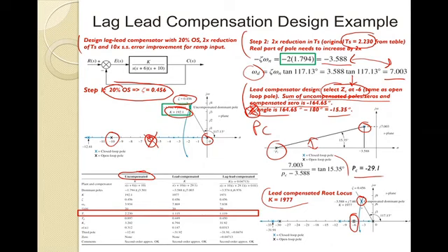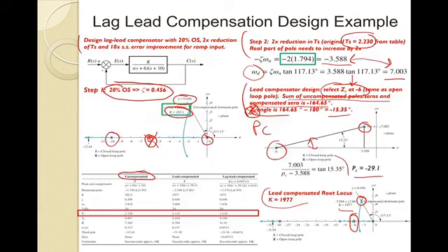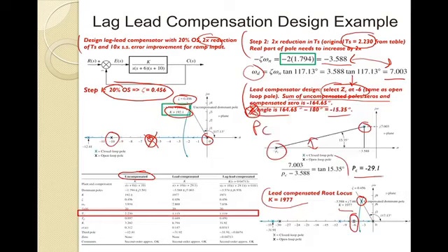As I walk through this, I have a pretty high gain here associated with that lead compensator. I then do my simulation, and I can compare the uncompensated system here in black versus the lead system that I'm showing here in blue. And what you'll see is the settling time has indeed come down by a factor of 2. 2x reduction was our goal. And again, you can see this if you look at the table. Visually, it looks like a factor of 2, but here on our table, you can see that factor of 2 going down as well.